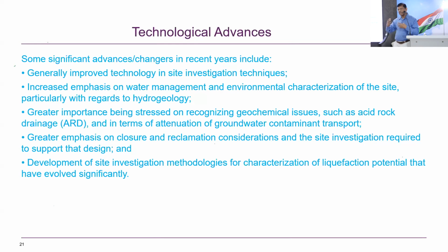One of the things I have discussed with a lot of people is they say, how can I determine the undrained strength during design? I don't know anything. My answer is, how do you get the drained design parameters? You don't have anything either, but you get some drained strength. One aspect is that the variation of drained strength is very little. It doesn't vary that much, so you can use it conservatively for the drained parameter. But undrained strength varies a lot.